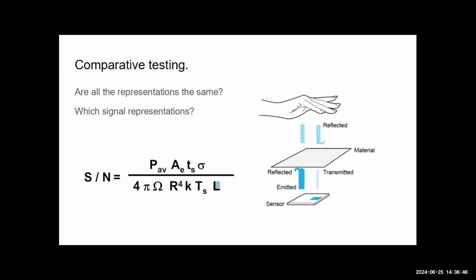Rather than using the raw signal, we can apply data representation methods to increase the signal to noise ratio. Here, we are going to compare different signal representation methods by accuracy. If we train with range Doppler images, what would be the accuracy? If we use micro Doppler images? If we use range angle images? This is what we are going to do.